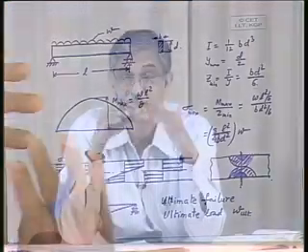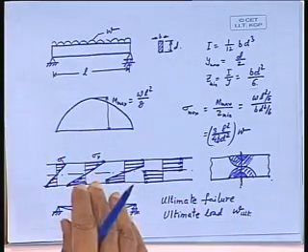So if you give a bigger flange, it will be better. There it is not the cross sectional area which is divided into equal parts, it is the force which is getting divided into equal parts. Here also it is the force which is divided into equal parts, but because the stress variation is not there and we consider the same uniform stress, that ultimately divides the cross sectional area into two equivalent areas.